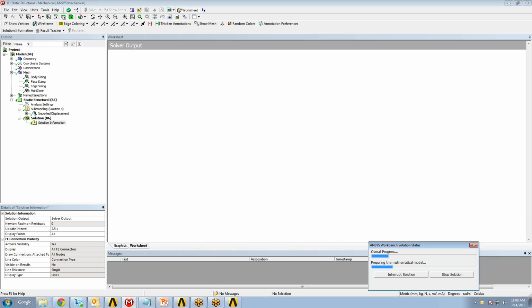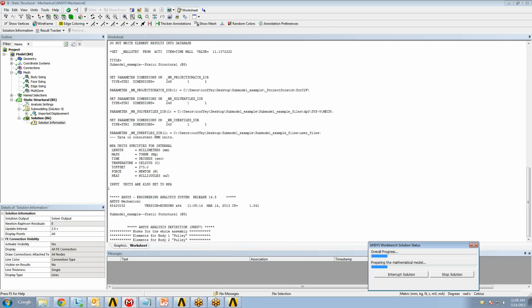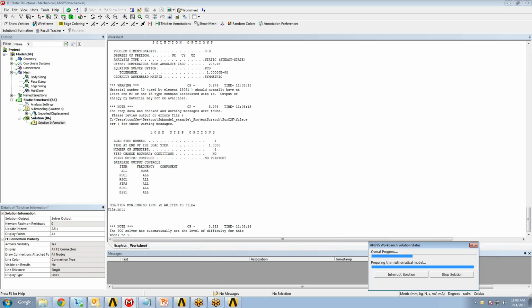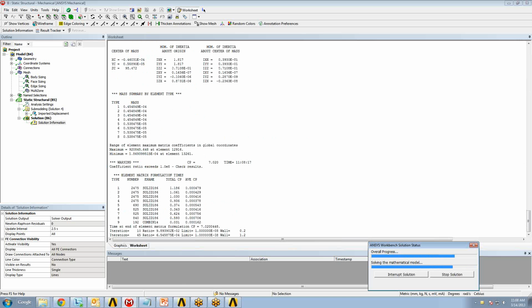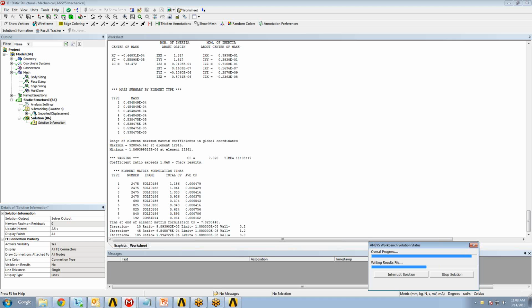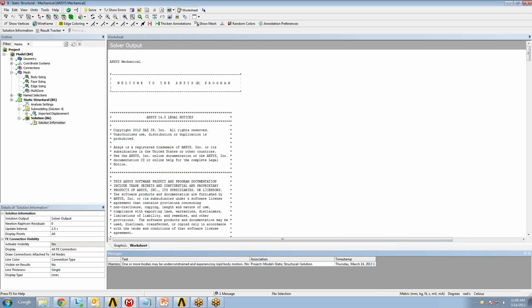And as I mentioned before, submodeling is based on Saint-Venant's principle. This principle states that replacing a load with a statically equivalent load only affects the stress distribution near the area of application. A common example of this type of exchange is modeling a distributed load applied over a small area as a point load. When analyzing a submodel, it is important to make sure that the loads in the submodel are statically equivalent to those in the coarse model. This is done by checking that the stresses on the cut boundaries in the coarse model and submodel are similar. Exactly how close the stresses need to be is up to engineering judgment, but it's important to always compare the stresses on these cut boundaries.